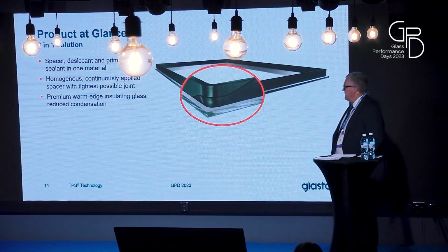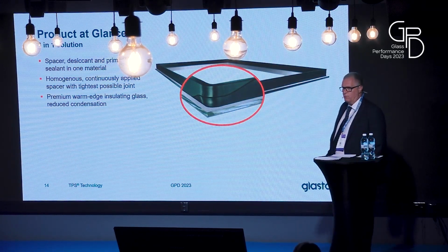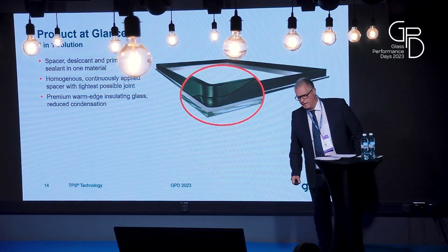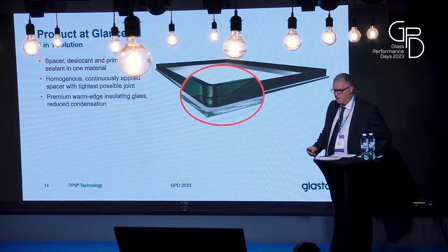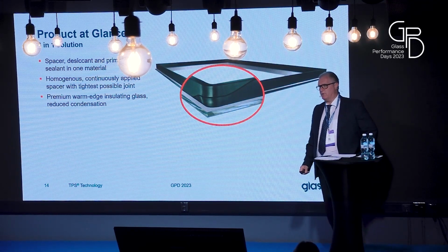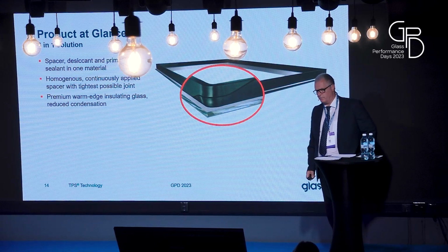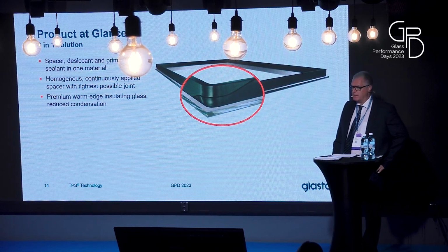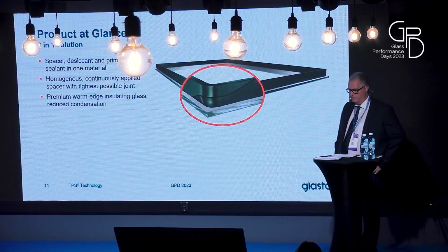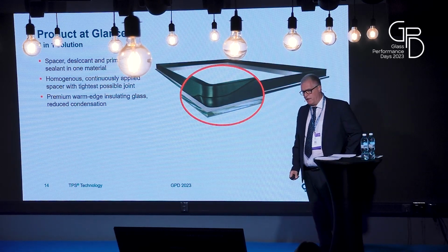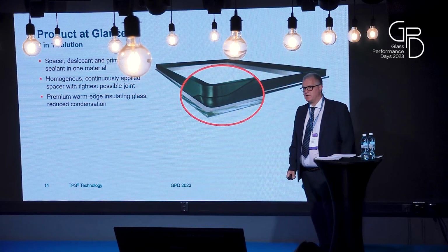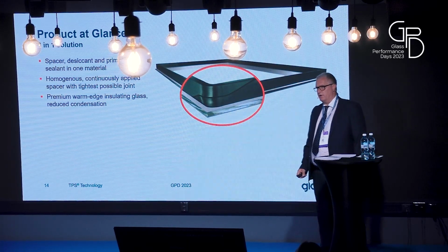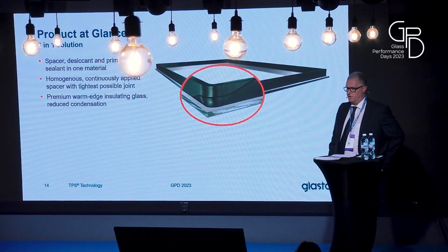The special thing is, this is a 3-in-1 solution. Spacer, desiccant, and primary sealant in one material. A homogeneous, continuously applied spacer with the tightest possible joint. And this then gives a premium warm edge insulating glass unit without any condensation.